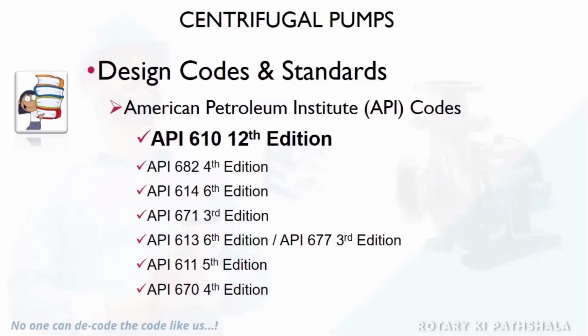Bearing temperature should not go beyond the limit. How will you come to know? If you are monitoring the bearing temperatures on a regular basis with an online system, you will come to know that if the bearing temperature is increasing, it means something is wrong with the lubrication system because bearings are not getting sufficient lubrication or bearings are getting overloaded.